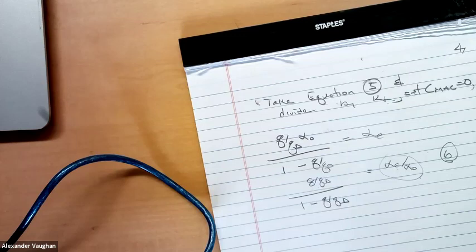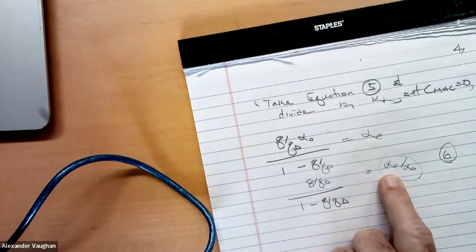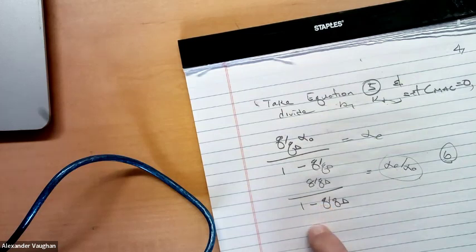Because if you get too close to divergence, the twist would be too big, you might see the yield stress of the material, and other bad things might happen. So enhancing the lift by allowing some twist to occur, by getting relatively close, but not too close to Q divergence, is not necessarily a bad thing.